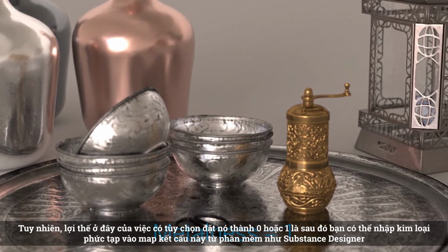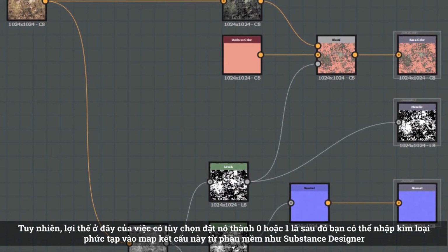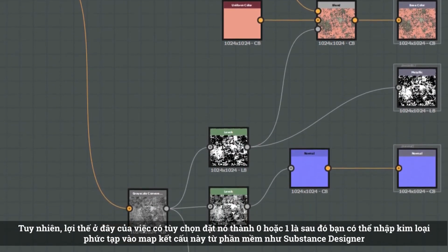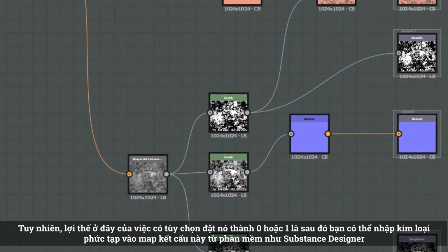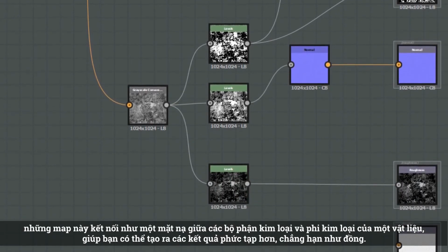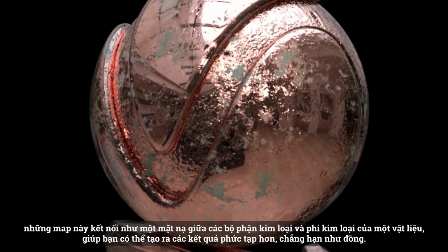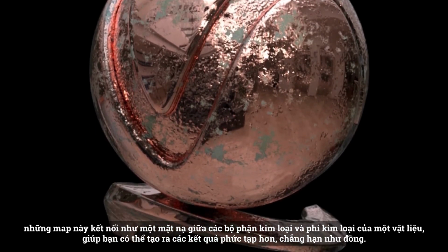However, the advantage here of having the option to set it to either 0 or 1 is that you can then input intricate metalness texture maps from software like Substance Designer. These maps can act as a mask between metallic and non-metallic parts of a material, making it possible to create more complex-looking results, such as corroded copper.